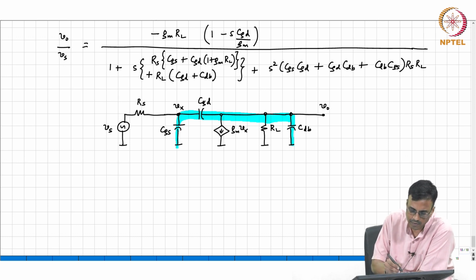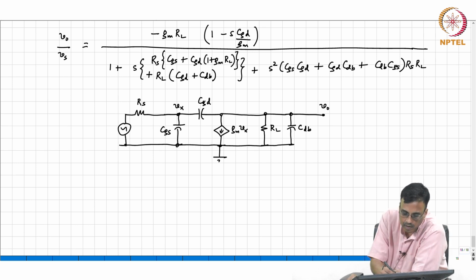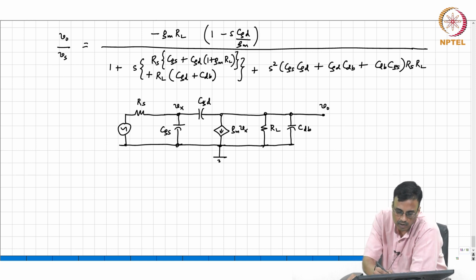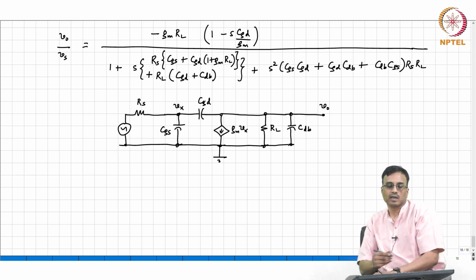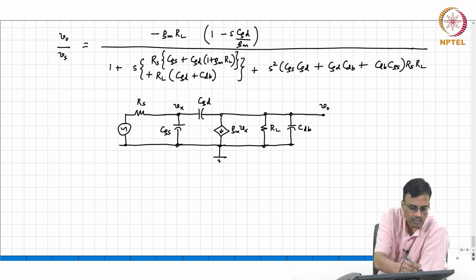Once 2 are specified, the third is determined. Basically, even though there are 3 energy storage elements connected in a loop, all 3 capacitor voltages are not independent, and therefore it is still a second order system.